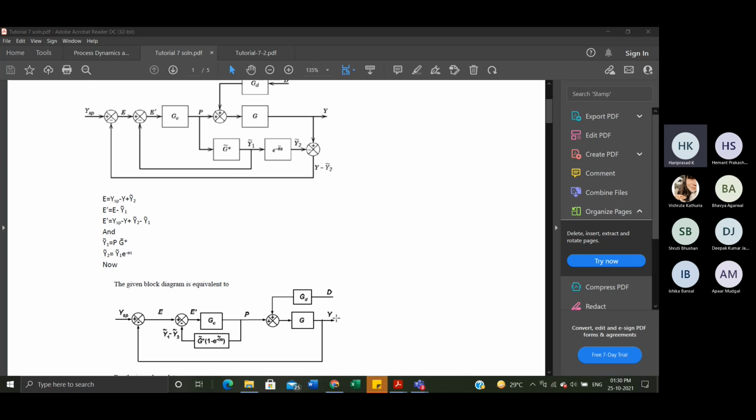So the key aspect generally in the feedback loop is that it would be a smooth feedback loop. There won't be any comparator in the feedback loop technically in most of the standard cases. But what is the prime problem that we have seen? It is the addition of this comparator in the feedback loop, which is non-standard. So the first thing that we have to remove is this comparator in the feedback loop, where y tilde is getting subtracted from y, because that is not in the standard form. The standard form is y going back and getting connected to ys2.